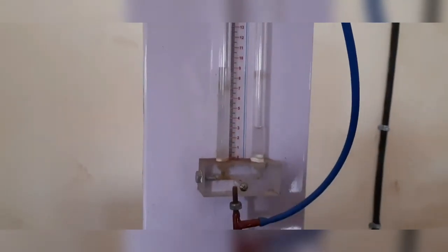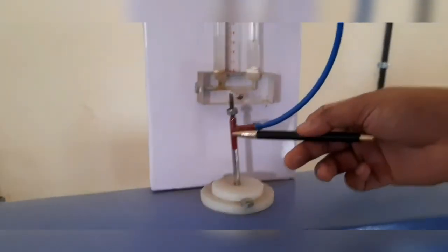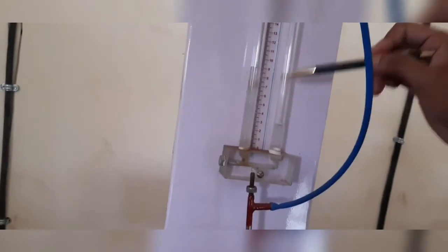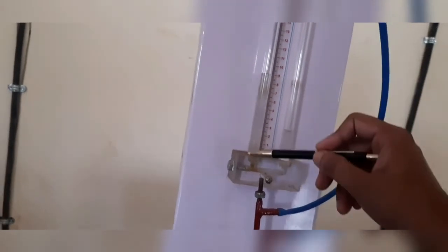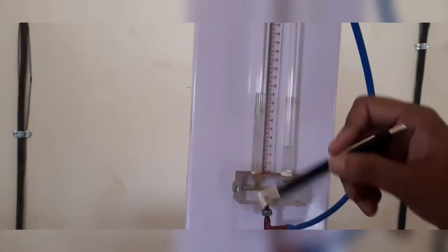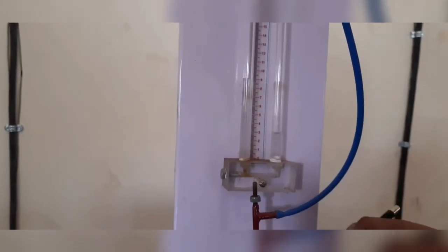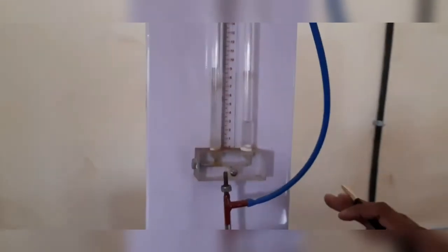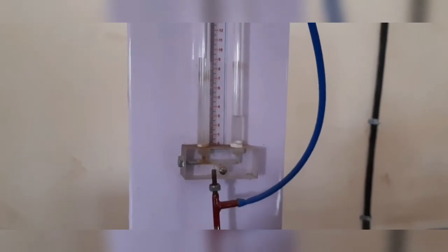When the air flows, this is the output through which the air will flow like this. Then with this pressure of the air, this is the difference. This one is the H2 value and this one is the H1 value. Through this H1 and H2 value, we are getting the pressure difference. That is V. V is equal to root over of 2gh. We are calculating the V. Then we will take how much amount of rate of flow will take place.